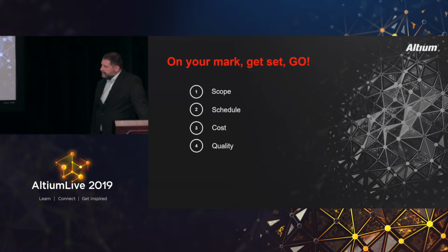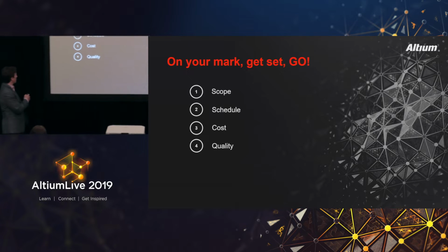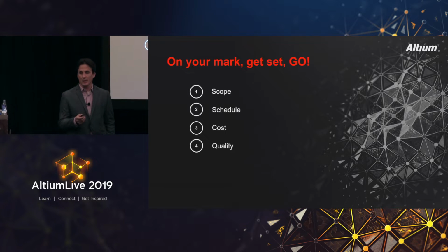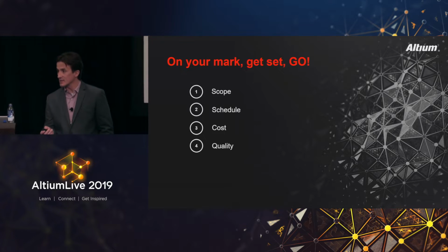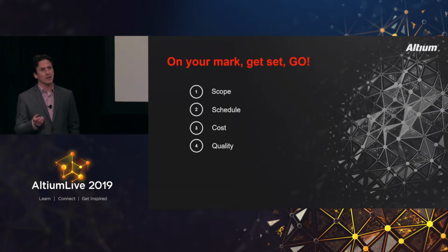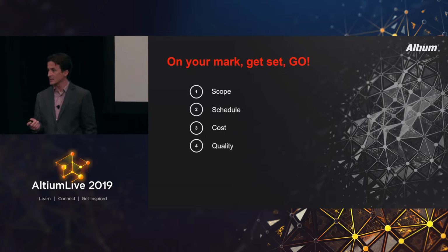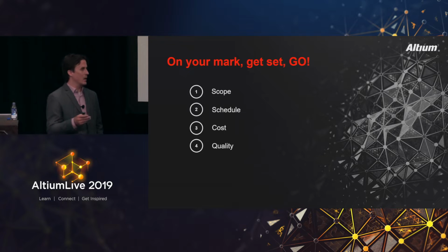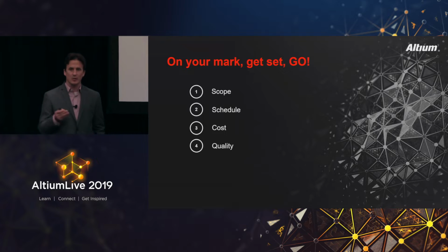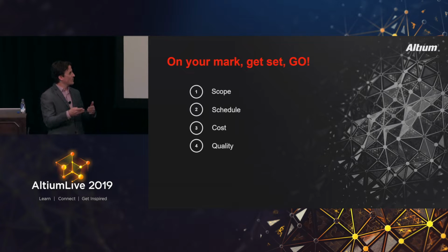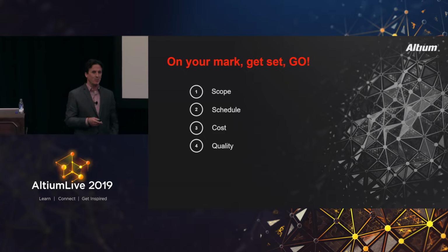Yeah, one thing I would say is one of the common things that I see a lot, and I'm a firm advocate of resisting this: if there's a really tight schedule, a lot of engineers cut corners in the process, thinking that they can get something to the fab shop faster. When you're dealing with a board that has a 21-day turn time just for fab, and you've got a mistake that you can't fix, then that extra time you got by cutting corners will definitely come back to bite you.